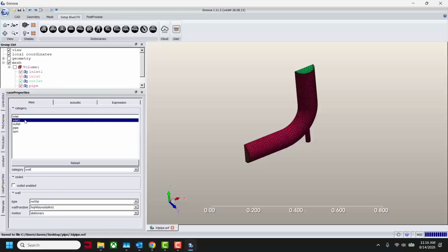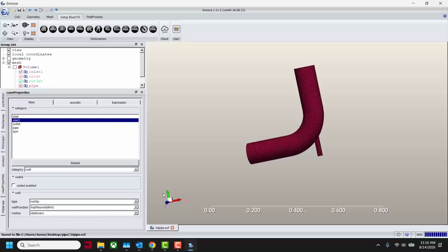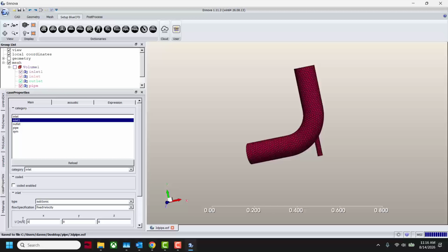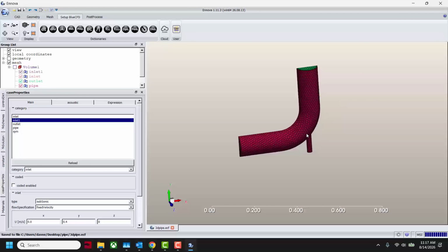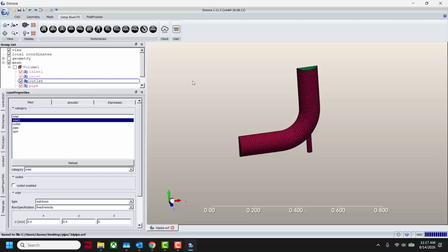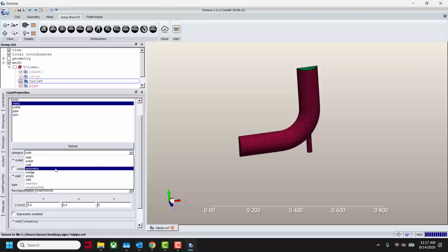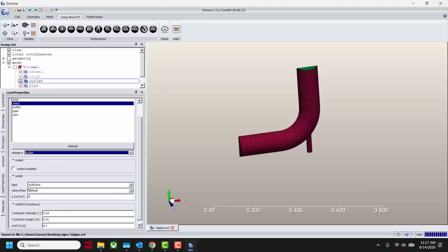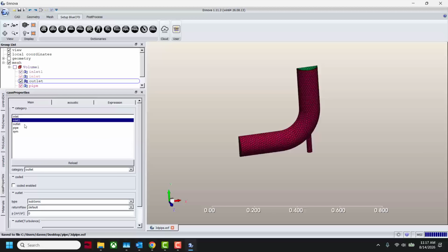We can go to inlet 1. Now inlet 1, of course, is this bottom guy, and he's in plus Y. So again, define him as an inlet, and we don't want it 1 there. We want, like, maybe, I don't know, he's pretty small, so 0.4 going up. So I've got 1 meter per second going left to right, and 0.4 meters per second little jet shooting in there. So then the outlet was a little green patch on the top. We can set that as a standard outlet in OpenFOAM, and we can see subsonic default. Just leave everything the way it is.